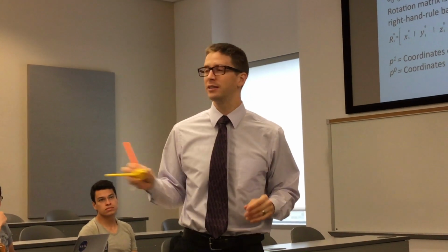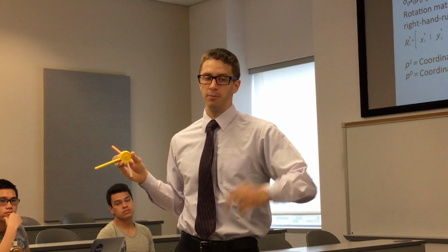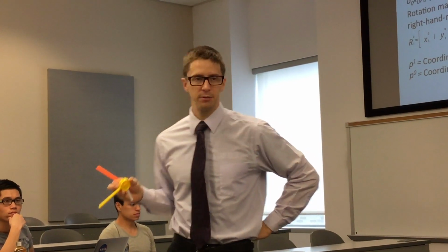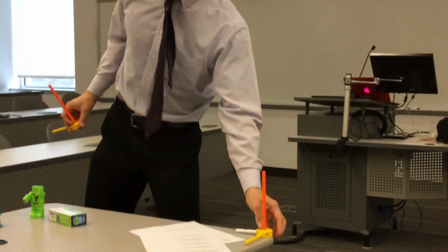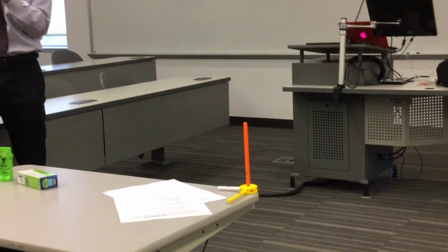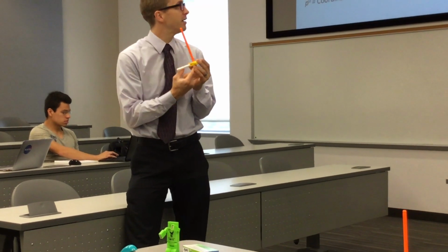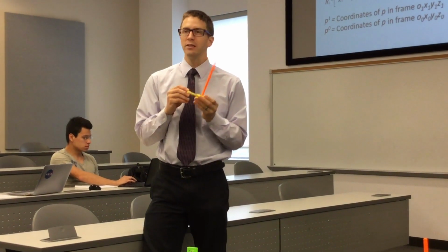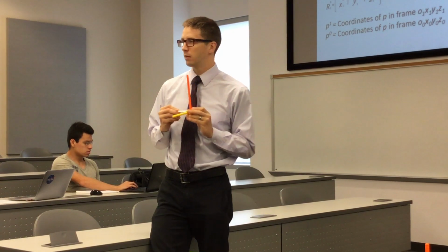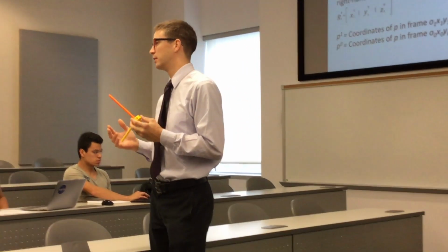So I need to know what is the x, y, z displacement of this origin with regard to some base frame. This is going to be my base frame. We're going to pretend that's strapped down right there. We're not going to move it. We need to know the XYZ displacement of this point, and then we also need to know what is the orientation of these vectors? And in order to fully specify the orientation of these vectors, we need 3 numbers.